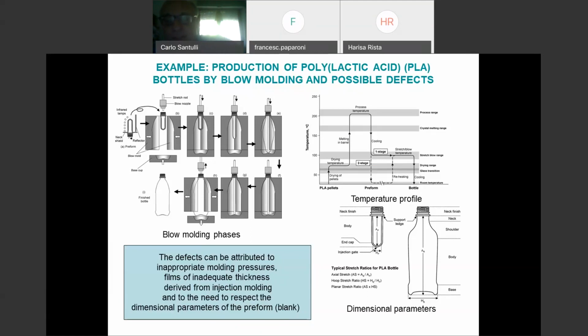you have an additional problem with polylactic acid pellets, as you can see here, drying of pellets, which means one important thing: nice having bioplastics, but they absorb some moisture. And therefore you get to 70, 80 degrees or so, depending on that temperature. So moisture is dissolved, and in practical terms, you are then able to melt them, to process them at a considerably higher temperature than the melting range, which you have here.